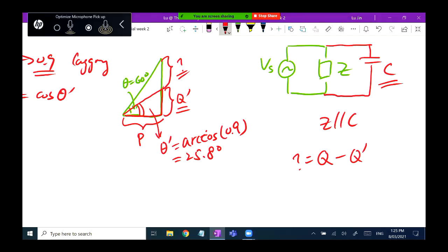Does active power stay the same? You mean the real power, right? Yes, it must, because the question says we are adding only a capacitor or capacitors. Capacitors cannot consume any real power. No matter how many inductors or capacitors you add into the circuit, you are changing only the reactive power, not the real power. Is that okay, Ben? Yeah. Okay, this is the idea here.